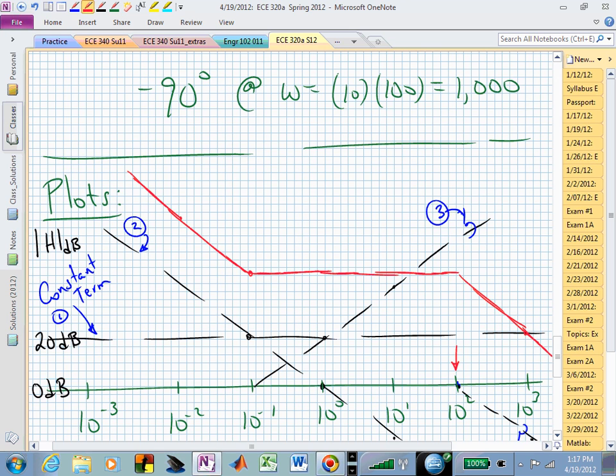And so now if you're looking at the peaks and the valleys, or the maxes and the mins of this cosine, those are going to be going at 1 radian per second up to 10 radians per second, and the input will be scaled by 100, and they will all be aligned in time. The peaks will be with the peaks and the mins with the mins. Questions on that? And you can tell a lot about what your system is doing from the Bode plot.